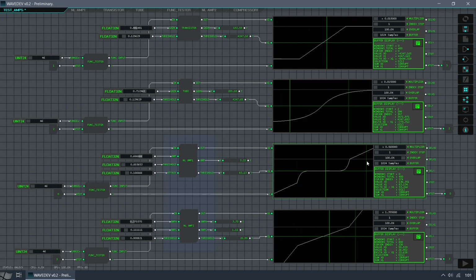I must confess that this is not my favorite method for noise suppression, since these blocks are also wave shapers, therefore distorter blocks. That's right, they distort the signal in order to reduce the noise. But this kind of distortion has nothing to do with the effect we are looking for. The distortion that derives from these functions is called crossover distortion, and it is incompatible with the distortion produced by our main functions.